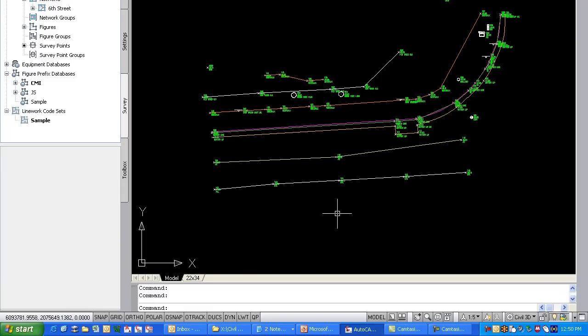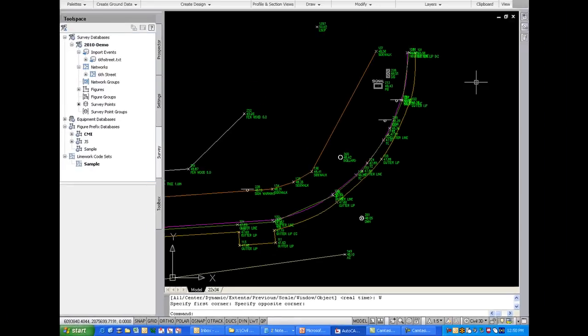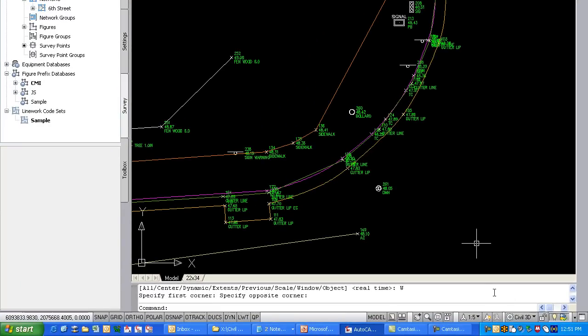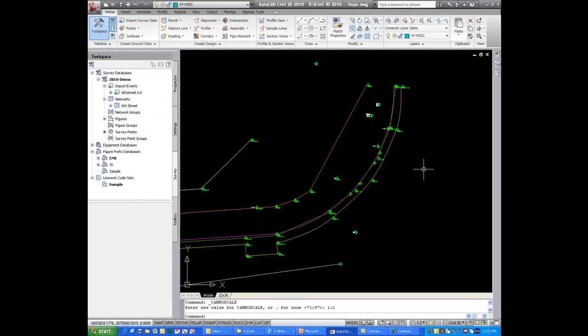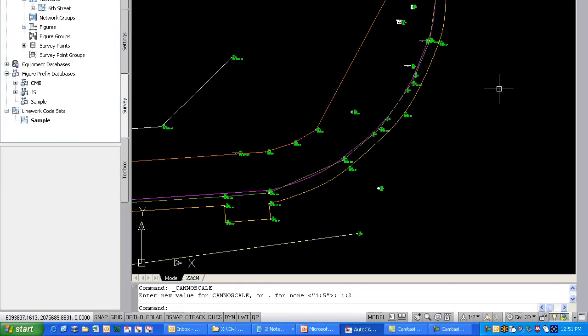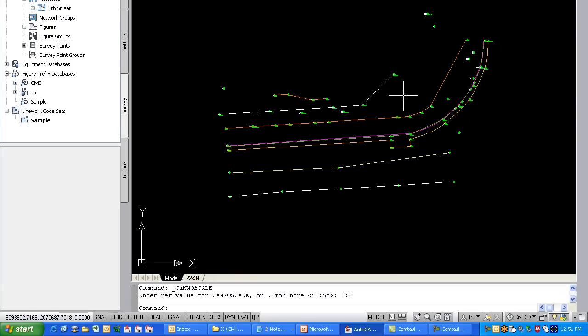And if you take a look on the right hand side, it automatically did an arc, a curve starting with the point 101 all the way down here. It did the same thing also for the magenta colored TC line. I didn't add the BC EC for the flow line, so that's why you see it still with the straight line segments here. Let's go ahead and reduce the size of these points so I can work with this a little easier. Okay, so there you get the general idea with the BC EC and the coding. And again, we're just working with point files. We're not even working with field books. So what else can we do with this coding?